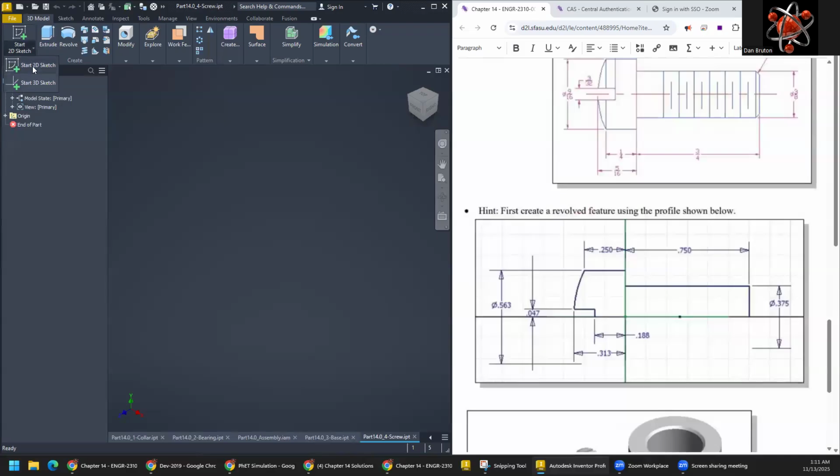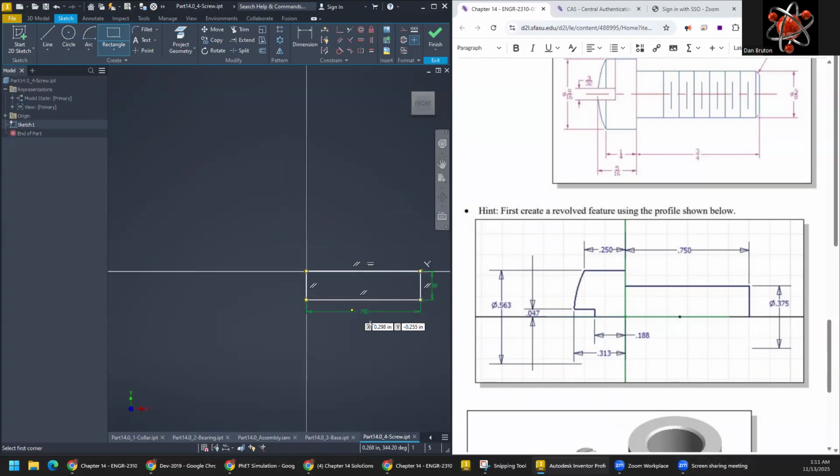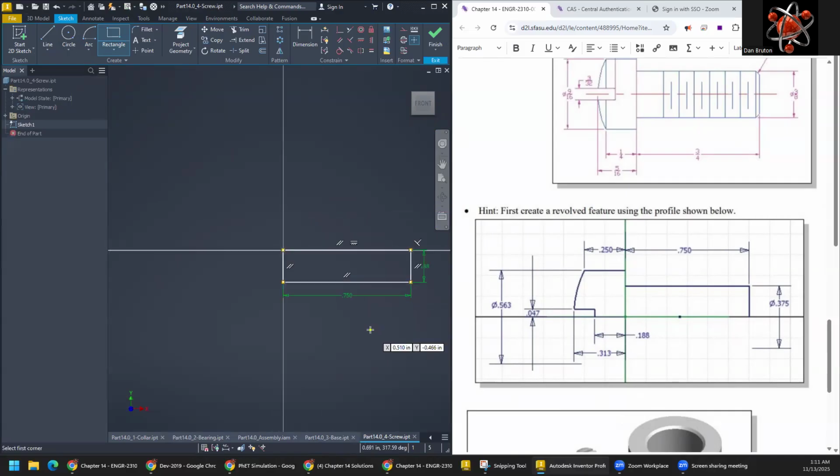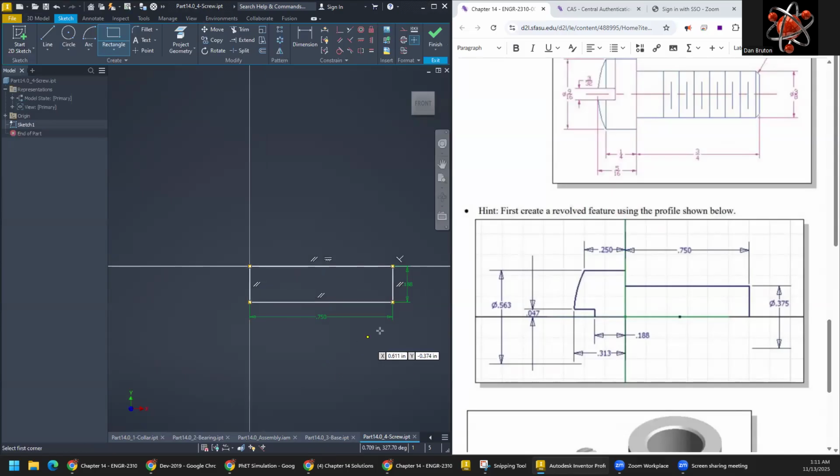And so they're saying just make a shape over here that has a rectangle and then some arcs. So we'll start with the rectangle and we need this one. And you see it's highlighted up there. I'm going to put 0.75, hit the tab key and type in 0.375 divided by 2 for this one over here. So hitting the enter key, I have it placed down there. And of course, I put it in the wrong quadrant. I really wanted it to be up the other direction.